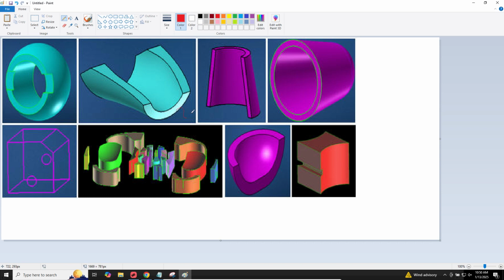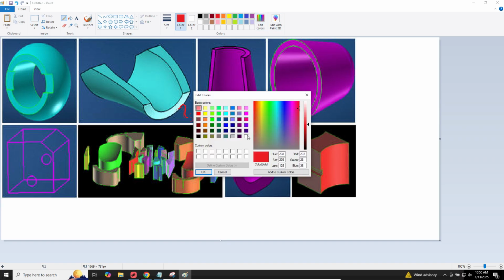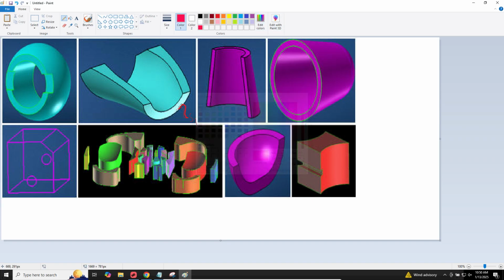So here, this example, we'll go ahead and call it S1. Let me increase the thickness of this. So you know what? I don't even think that's right. Let's go ahead and move this here. So this could be side 1. But here, if you look at this opposing side, where is side 2? Here, what I would do is create a partition. Let's go ahead and create a partition here also. So this face, if you will, is my S2, and then this other face is my S1. I can go and create a hex mesh here.